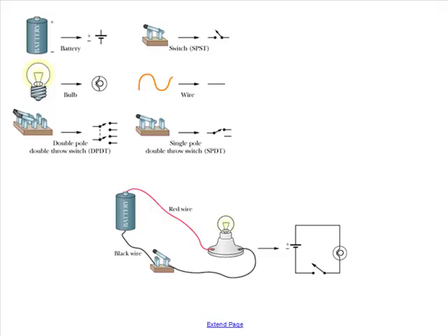Okay. Now, if I want to draw this case of a battery with a light bulb and a switch, I could draw this drawing here that actually looks something like what it would look like on the table, but this drawing is simpler to draw, simpler to see what's happening. It's got a battery represented by a long line and a short line. It's got a few wires connecting it to the light bulb, another wire connecting it from the light bulb to the switch, and then from the switch back to the battery. So you should try and become proficient at reading circuit diagrams and being able to recognize what they mean in terms of actual wiring.